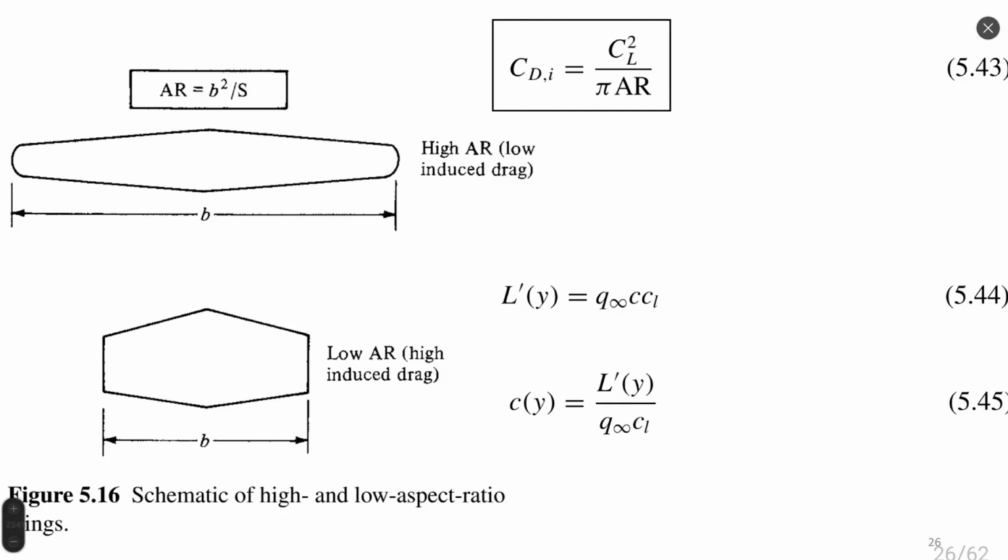Okay, with a longer wing, you need less energy to fly. With a shorter wing, smaller aspect ratio, you need to apply more energy on your engine to fly with the same velocity, same characteristics. This is why gliders or airplanes which could fly long distances, low velocity airplanes, have very long wings, because induced drag in such cases could be significantly reduced.